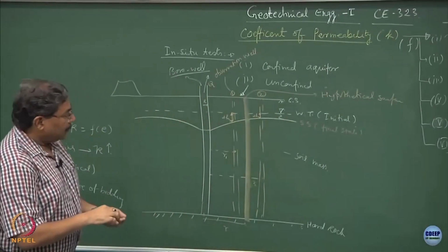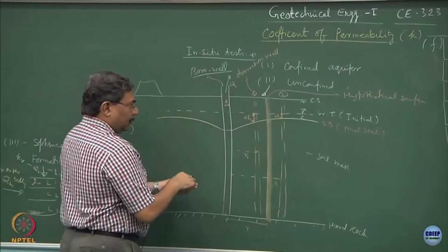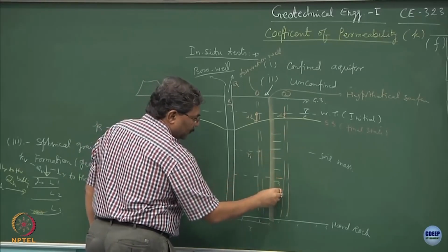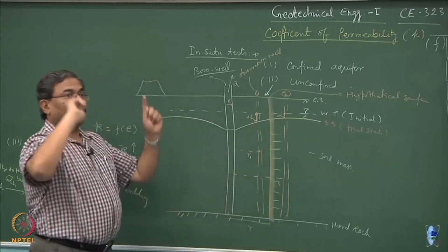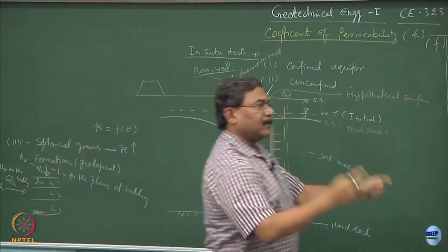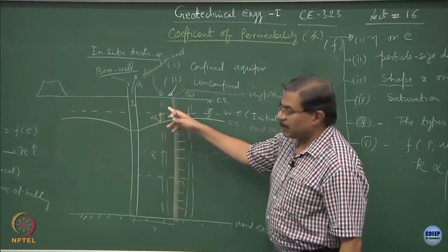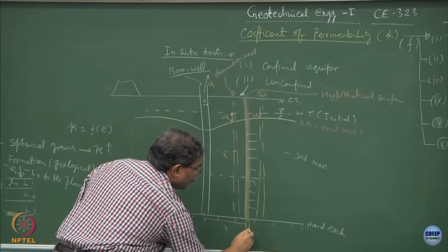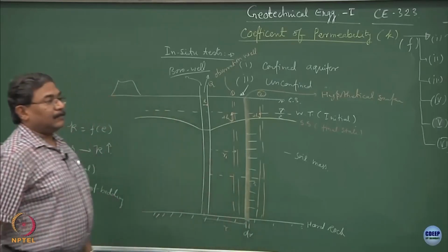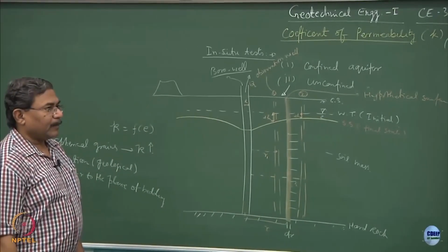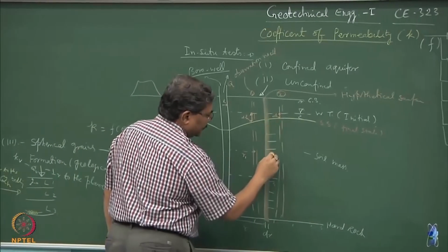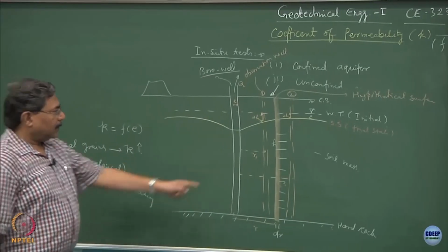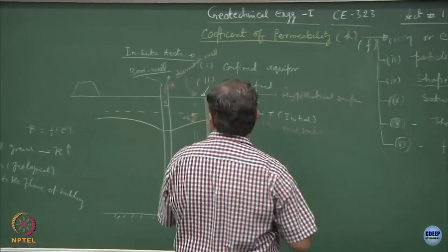I hope you can realize that when you are pumping out water, the discharge is going to take place perpendicular to the surface. Is this correct? Have you understood this? So, this is a sort of a cylindrical curved surface, perpendicular to this the discharge is going to occur. So, if this is R and the thickness of this element is dr, clear, the height of this surface is, let us say, h, fine. Can I write a relationship between Q